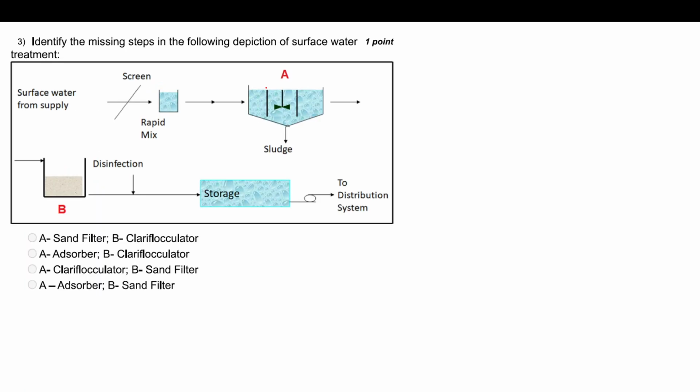So now moving forward, a process of aggregation or accumulation of colloidal particles to settle down as a precipitate is known as dash. Coagulation. Yes, coagulation. It allows the particles which are in suspension form to aggregate, which is nothing but coagulation. I have told you the mechanism where it reduces the surface charge and allows the particles to come closer and form bigger particles.